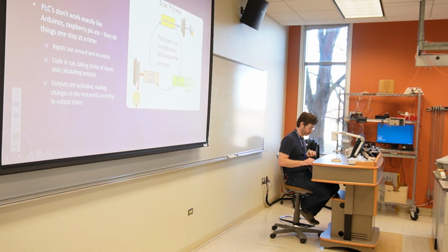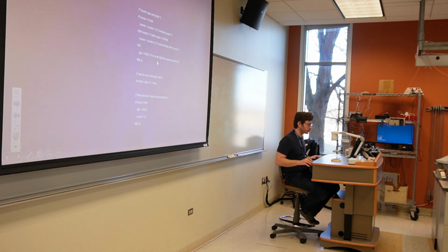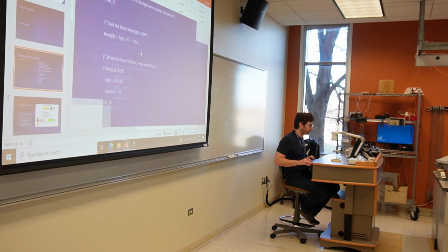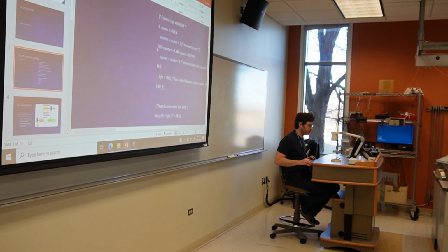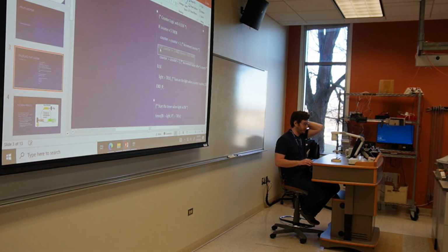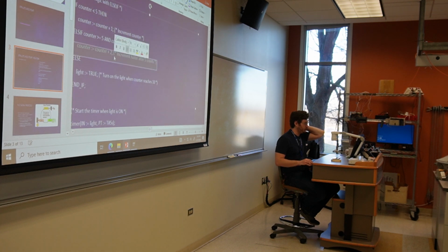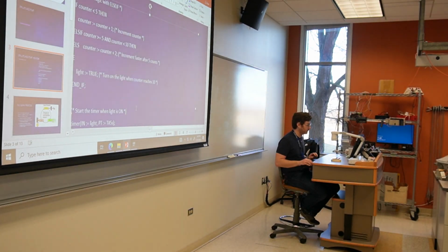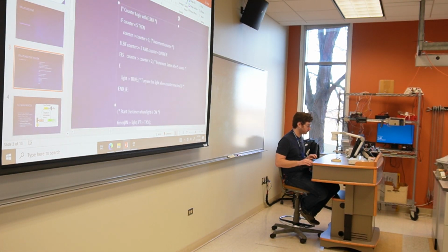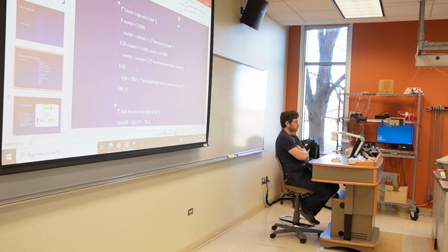And here's an and example. Can you see it? Oh, nice. There we go. Okay, so here's the and. This is the else if, but you can imagine this says if counter is greater than 5 and counter is less than 10, then do the thing. This would be like turn your output on, otherwise turn it off. Okay, so then it would just be if LEDY or LEDR, then LEDG equals false, to turn it off. Right.